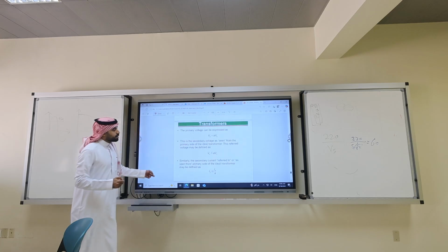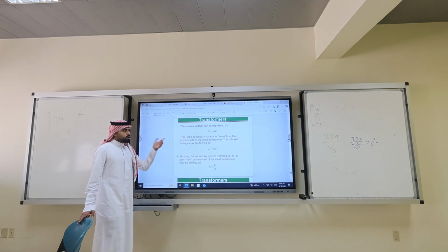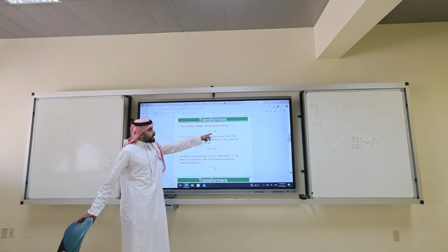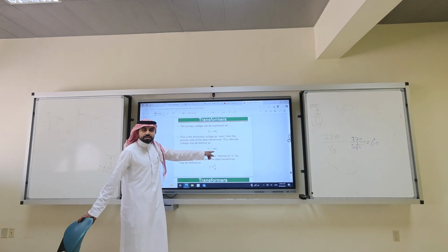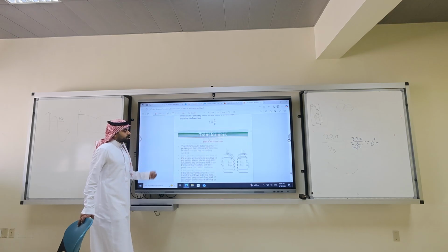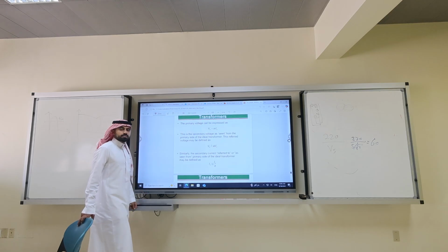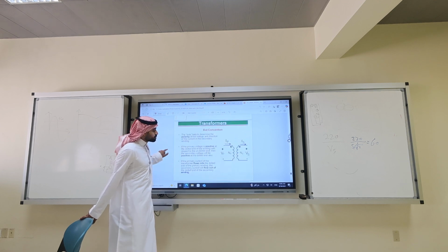Okay? Of course, the secondary voltage can also be reflected. So we call it VS prime, which is a VS. You can call it VS prime, but you can call it a VS. Prime means reflection. Or IS reflection, you just divide the current. Any question? Okay, with that we'll stop at the dot convention for next lecture.